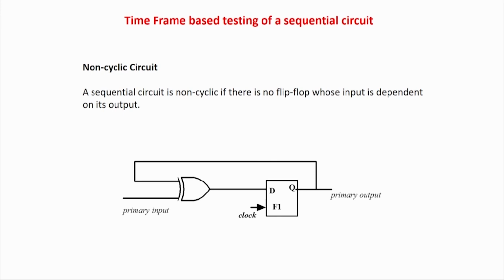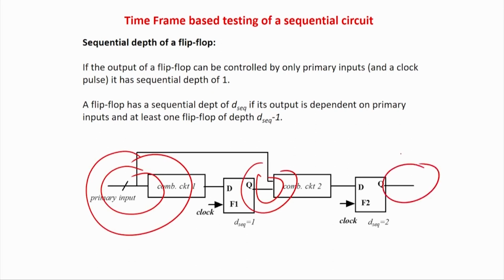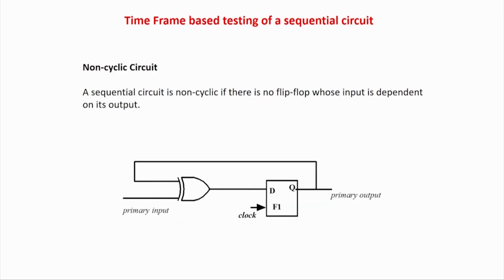But you will be able to do it. That is guaranteed. We have seen that basic idea in this result: first you control level 1, then again you use the primary inputs, this is already controllable, so you can control the next one, and in an inductive manner you can do it. But if there is a cyclic flip flop somewhere, then that flip flop may not be controllable. So the only way to control such flip flops is either by scan or by set reset. So that is the basic idea.